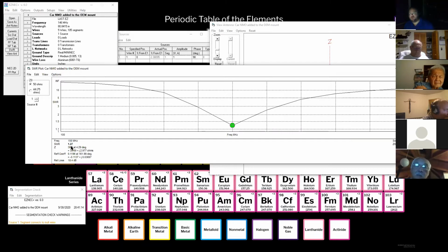So this confirms what we already know from antenna design. A dipole has a characteristic impedance of about 70, 75 ohms. If you bend the dipole, that impedance changes. So that's why your V antennas have a 50 ohm impedance, because you've lowered the radiation resistance by bringing those elements closer together. Well, now I'm at 90 degrees, but I added a whole bunch more elements. So this thing can conduct to itself very easily. So now we're at 38 or 39.8 degrees. So we're matching better, but we've gone too far in the other direction.